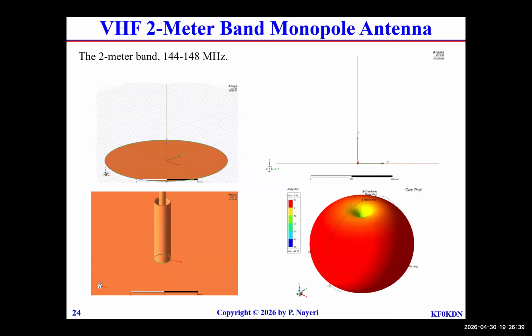As mentioned, this ground plane is so small compared to the wavelength. What you want to have for a real monopole is a ground plane of at least 5 wavelengths in diameter. And in that case, there would be very little field below it, and you would see a lot of diffraction. But I actually didn't simulate that, as you can probably tell here. I intentionally set it up with a student version. The student version is limited in memory. You would not be able to model something that large. So I gave you something that you can model with the student version, and it would work. But no, your point is well taken.